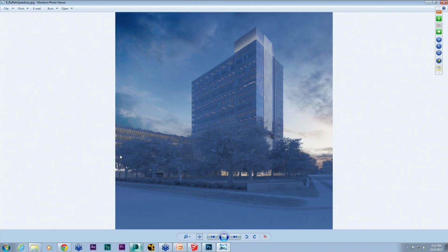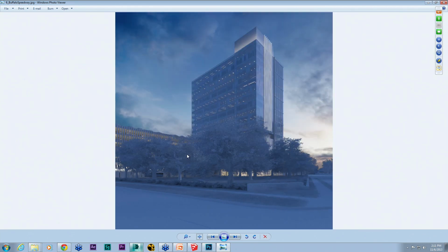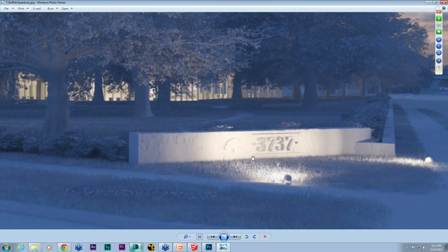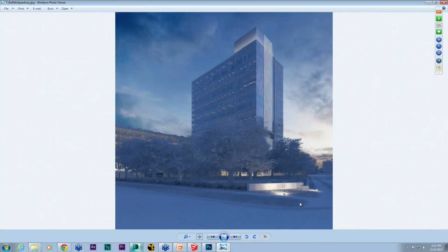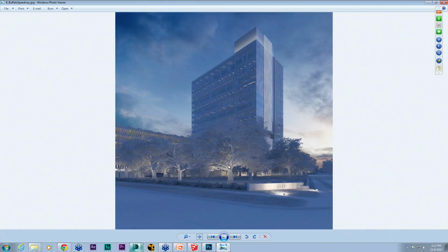Then we go through and turn on the garage, and they have some uplighting over here to get some ivy. And then we have the lights up front. We wanted to get some nice catch on the grass there, which I think turned out pretty cool in the final. And then the tree lights. And so one of the things I did for this one was make use of the V-Ray Light Select. It's one of my favorite elements. So I have a V-Ray Light Select for the trees themselves, so we can go through and mess with that later.